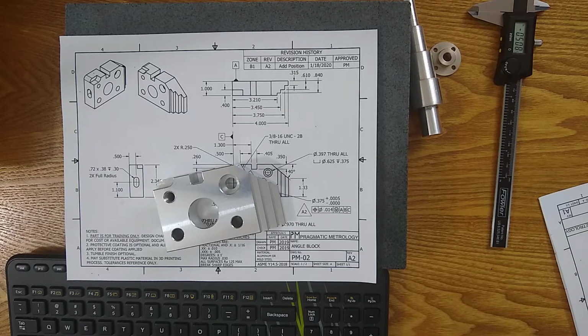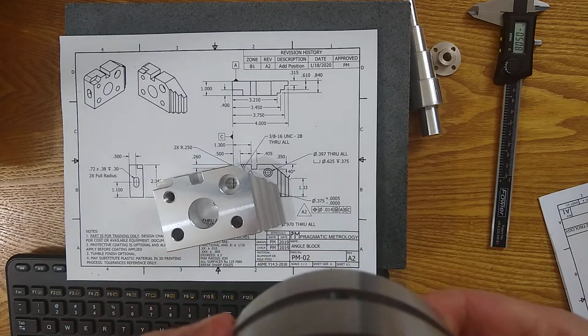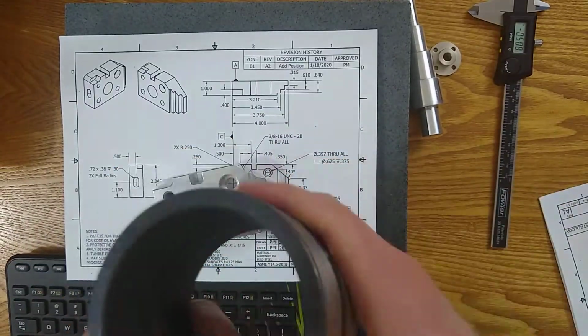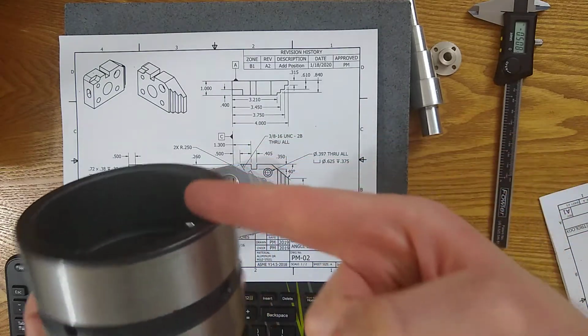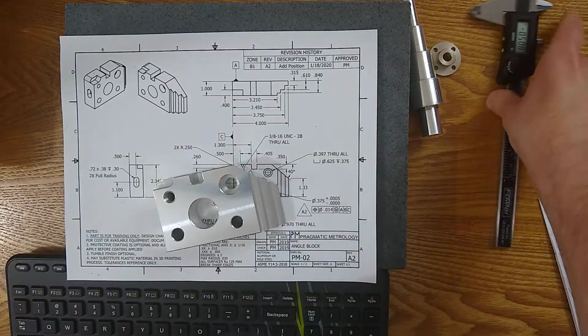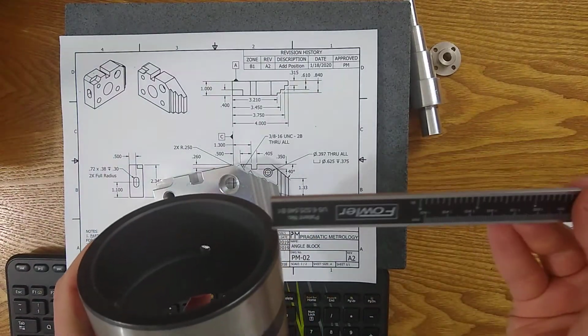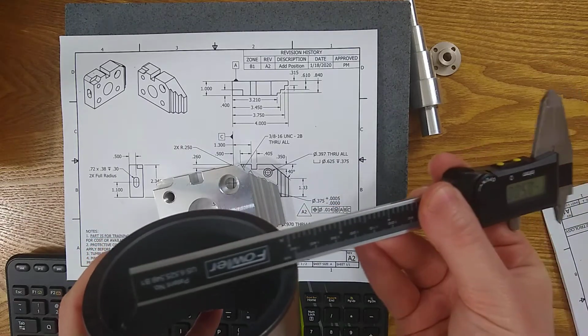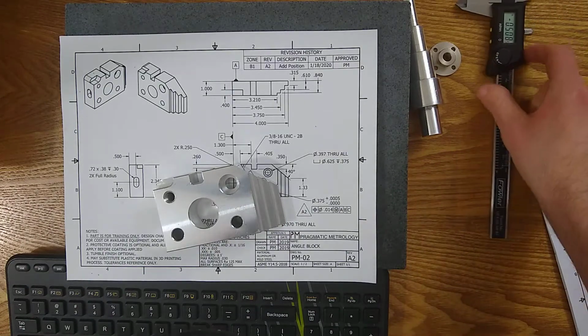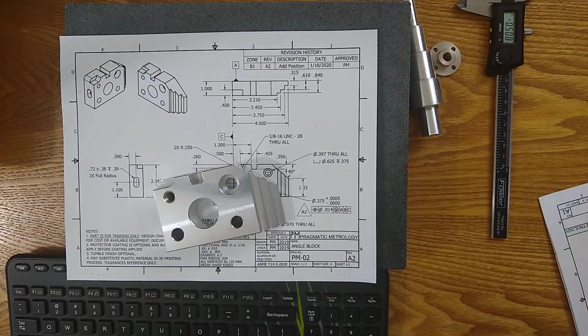So sometimes when you're making a part out of metal, or it could be any other material in industry, this part's got through holes all around it. Sometimes when you want a through hole to poke through one side, it won't go straight through on the other side. Instead, we call it walking. It'll start to poke through, and then it'll go at an angle and poke through at a location you didn't want it to. So the way to check for that is to check both ends, because both ends need to be in tolerance.